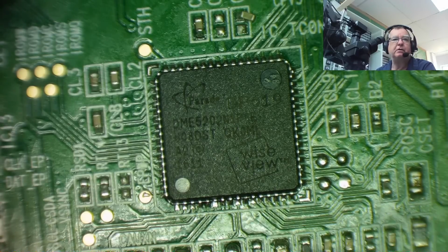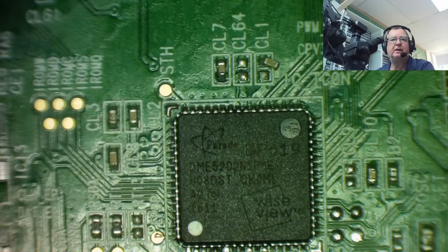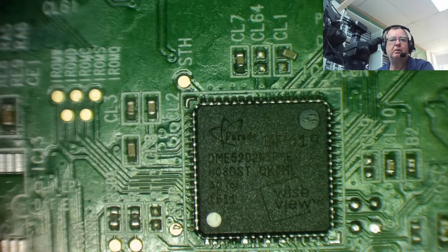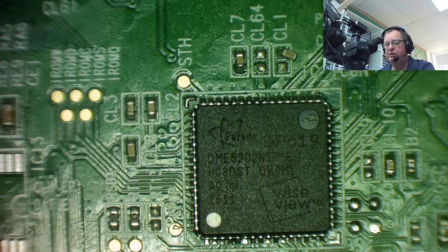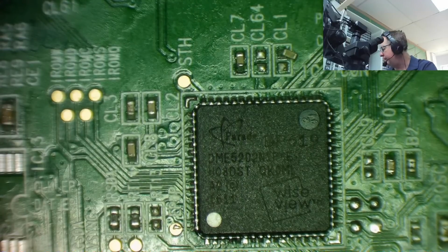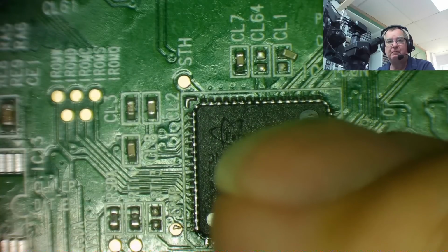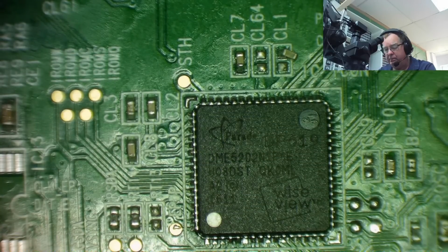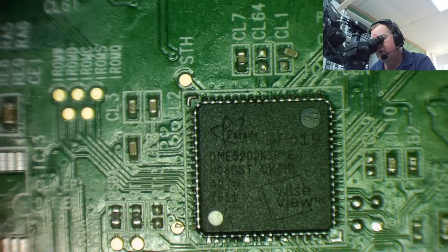They don't have any solder, so I'm going to have a look around this on the microscope, see if I need to put any solder on any more of the pins, and then we will use the hot air and just flow over the whole thing, just let it sort of bed in, and it should solder the tab that's underneath here. Remember, it's a big square tab, and help to flow the solder under the pins as well. So okay, let's get down the microscope and have a look.